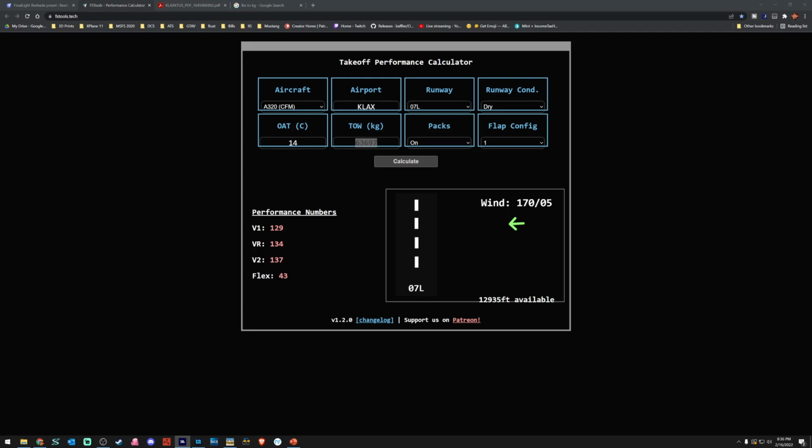And then from here, transition altitude, obviously make sure 18,000 feet in the United States. Anywhere else, make sure that you check up and verify what your transition altitude is. Thrust reduction acceleration altitude. This is the altitude above takeoff at which the aircraft will slightly pitch nose down, reduce the throttles to the climb position, and then accelerate to climb speed and continue its climb. Engine out acceleration, again, altitude above ground, at which in the event of a single engine out at this altitude, the aircraft would then level out and accelerate up to climb power and continue the climb.